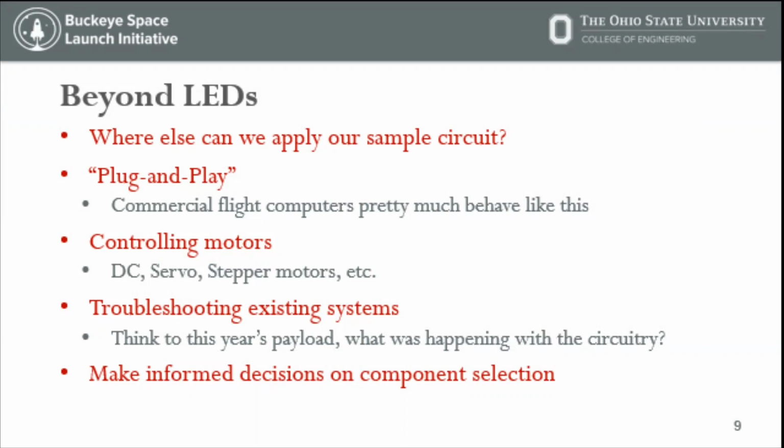A lot of things are like this relating to rocketry. Flight computers are like this. You know, the Stratologger, the Telemetrum, Easy Mini, Merlin Missile Works flight computers, you have to give them a battery, you have to give them a switch to turn it on. Beyond that, you just let them go. As long as you fulfill the requirements that they have, which we'll talk about in a little bit, they should work. You can also use them to control DC motors, servo motors, stepper motors, other motors, which is important for payloads or recovery designs if you're not using pyrotechnics.